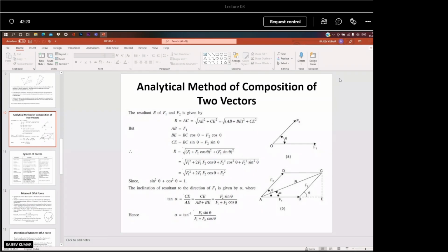Then whatever the force is, the weight is acting, so from that weight you draw the perpendicular distance, and with that perpendicular distance and that much weight and the horizontal force, you calculate and see what the moment is. In the same way, you calculate the y-intercept and the moment about that one point. X-intercept, y-intercept, this way you can calculate.